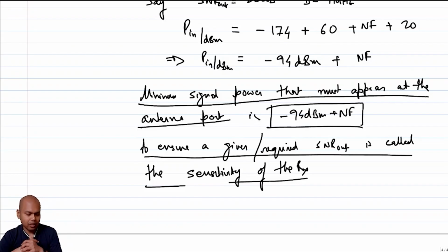That is why RF engineers, especially those working on receivers, are extremely finicky about noise figure. It is assumed that your receiver input is matched and that the LNA is giving some gain. The first thing, almost, if you are designing a receiver, is the first spec: what is your noise figure. So that is why your noise figure specification is extremely critical.